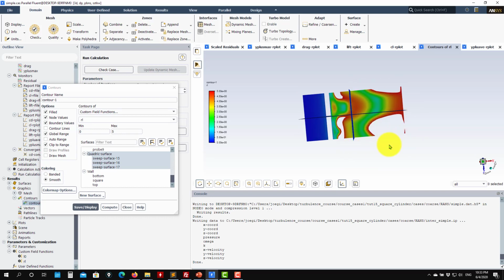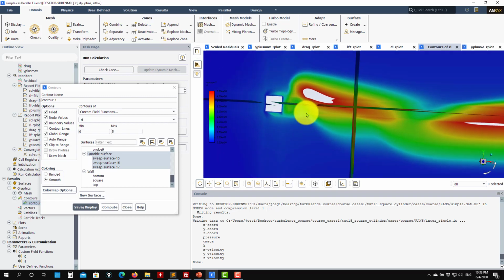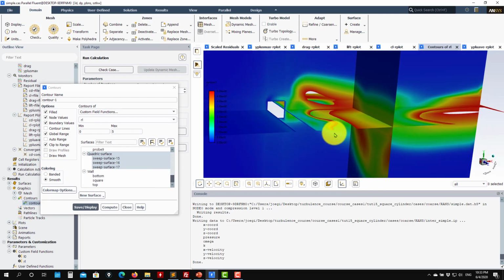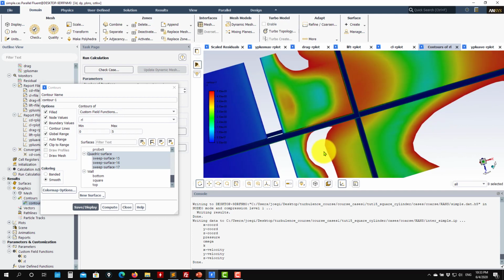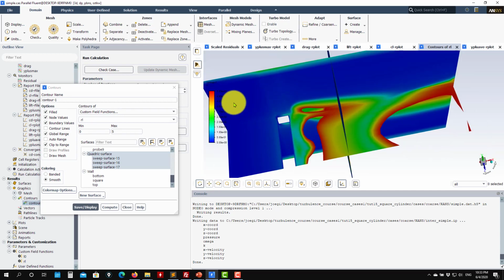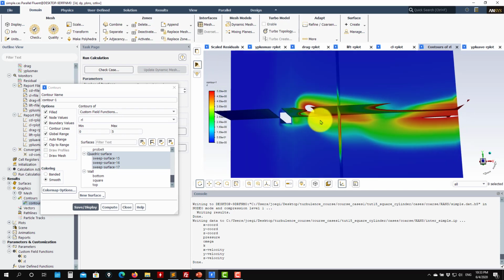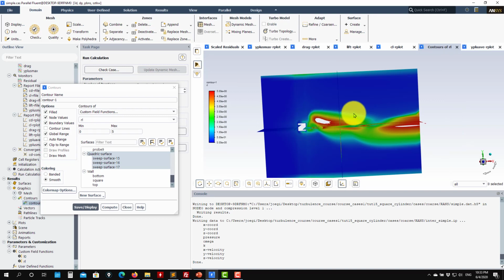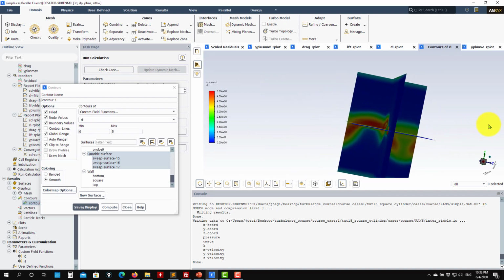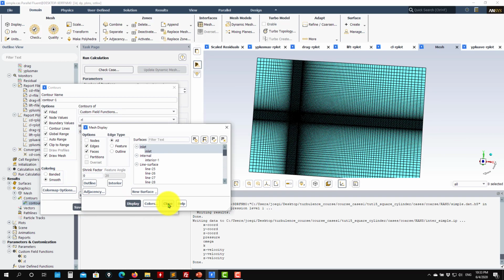So the largest vortices, see here, it's telling you that that is okay, but in general this mesh is not okay for this case. It's not resolving properly all your large scales. Probably the much larger ones, yes, but this changes in time, and this is not okay. What you would like to see is that all this region is not visible, meaning that all your work is well resolved. And if I plot the mesh there,